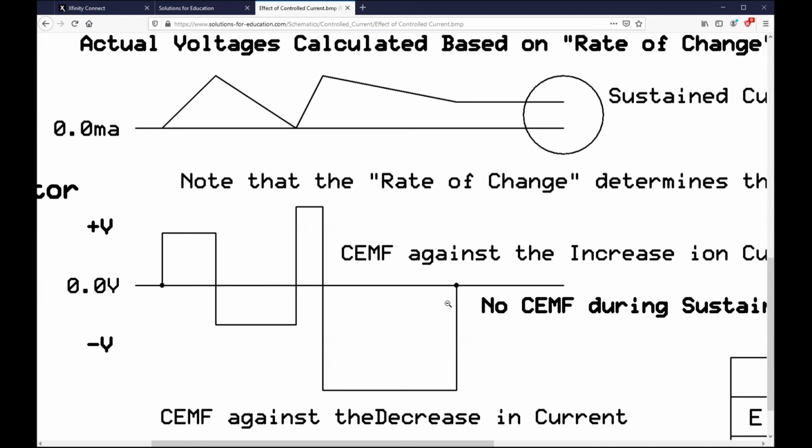Let me add just a little bit more to that. Sure. The failure mode for electrolytic capacitors that you might see on a motherboard, most often the case, is that the capacitor internally suffers some leakage.